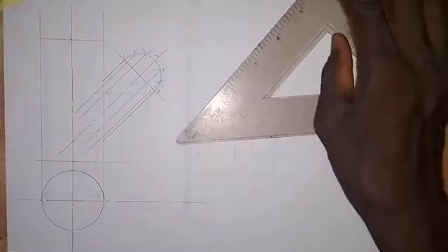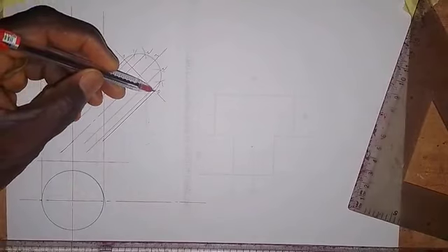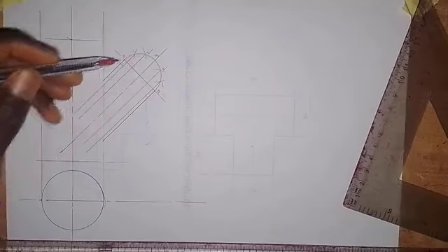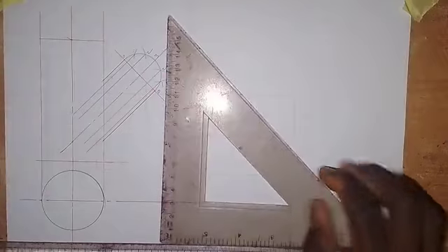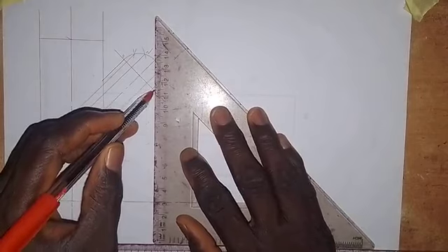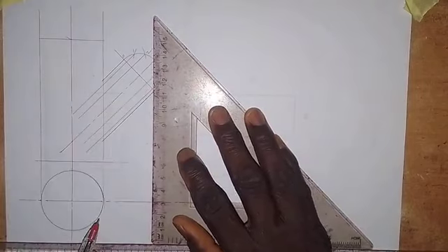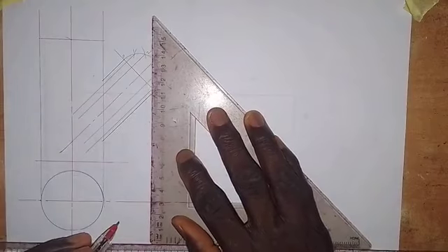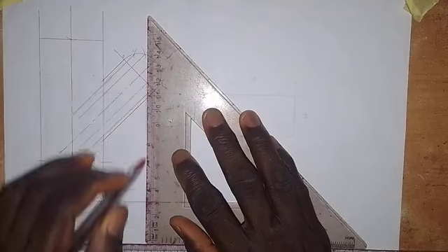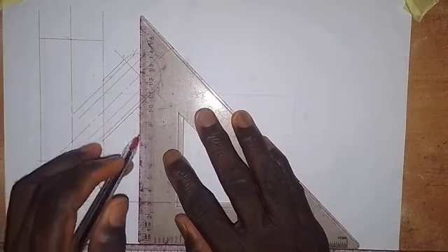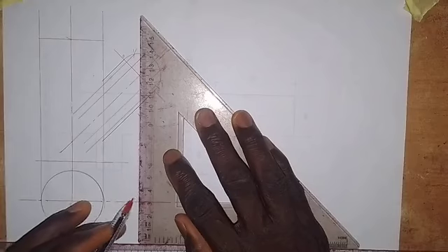So let's leave this for now. The next thing that we are going to do is draw a line from each point that we have here. Not on the semicircle, but on this line. So what I mean is this. With my set square set at point 0, I'm going to draw a vertical line from that point down here. Then from point 1, I will also draw a vertical line down, and from point 2 here, I will draw a vertical line down. From point 3, we are going to draw a vertical center line down here. Okay, so draw it down.